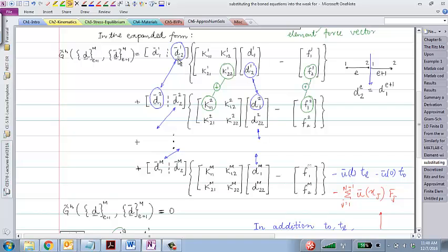If you note that the displacement at node 2 of element 1 is the same as the displacement for node 1 of element 2, which is saying that D12 and D21 are exactly the same, then you can pull that out common. And when we pull that out common, effectively what that means is that I will be summing up this entry with this entry. Similarly, I'd be summing up this force column with this force column. And note, of course, that the same logic works for the real displacements also.